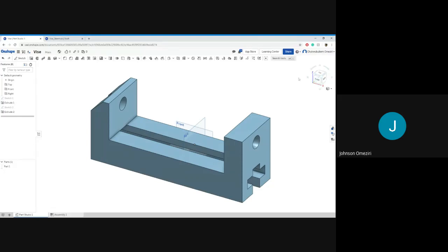On the top side, you see there's an object here that has a fillet, with the rounded corner. Click on it. Click fillet here. Select these two edges. You see, once I selected, those two edges came up here. Then I can select the value I want. How big should this rounded edge be? So I'll select 3 in this case.